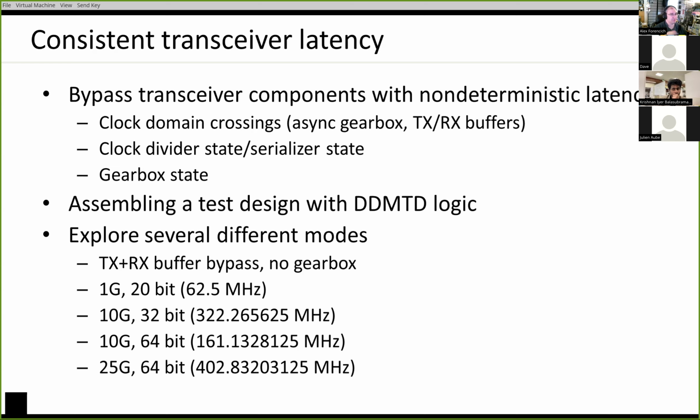So I'm working on putting that design together right now. I've had to port some of the XFCP components in order to actually talk to this, because I'm not building this on top of Corundum. I'm just doing bare transceivers for the time being. And then later on, we'll roll this into the wrappers and integrate it into Corundum. So hopefully I'll have more news on this in the next meeting when I actually get the thing working.